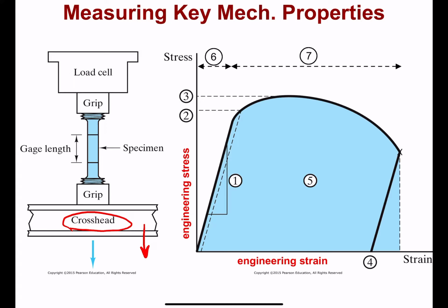And there could be a grip portion that may have some threading, for example, and a specimen could be fabricated to have threads there. And there would be a thinner portion of that material that would be defined very carefully in cross-sectional area and shape. This thinner portion, where the force would be focused on the specimen, is called the gauge portion. So the length that is all uniform there would be the gauge length.